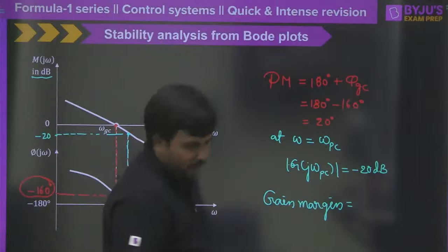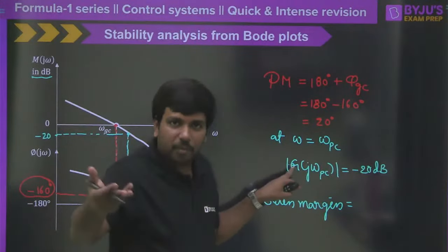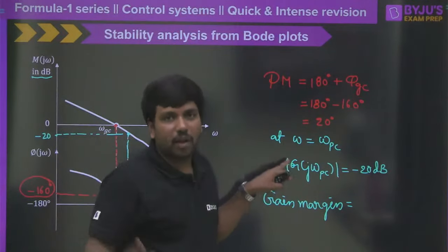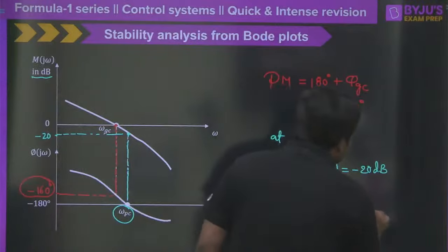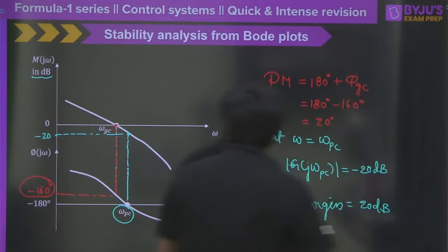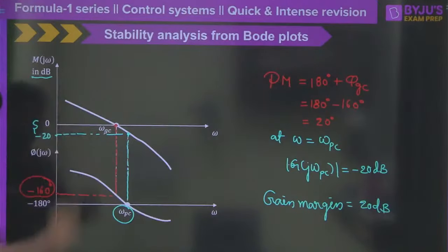Yes, very good. One reciprocal we will take in normal value, but reciprocal we cannot take in logarithmic. You have to take minus of this value, that is minus 20, so it will be 20 dB. So inherently it means you still have to add this value here, like this.